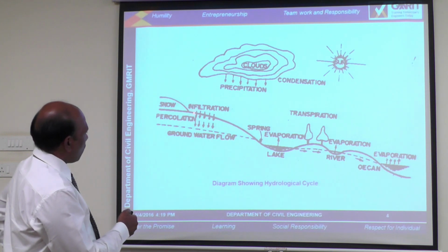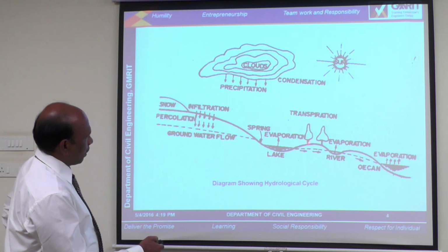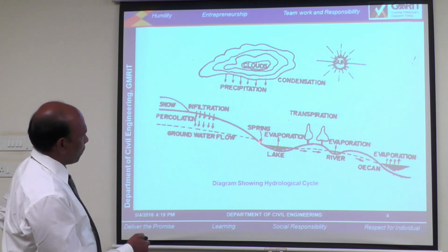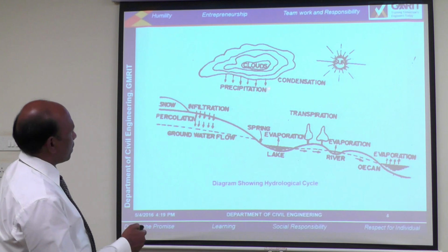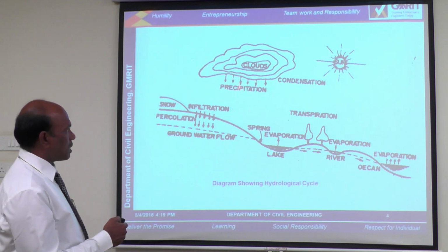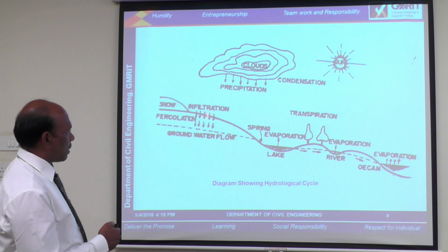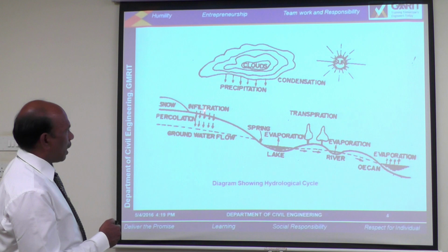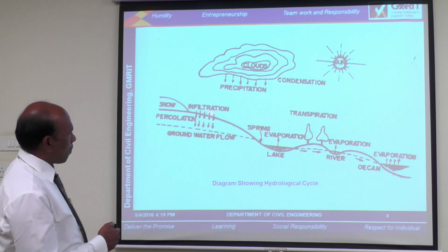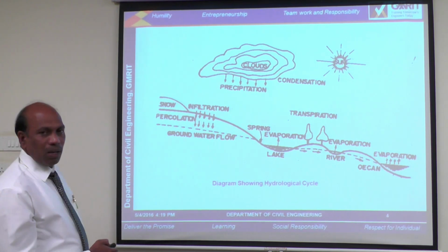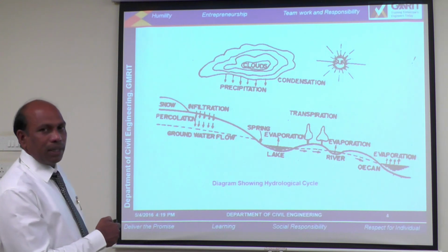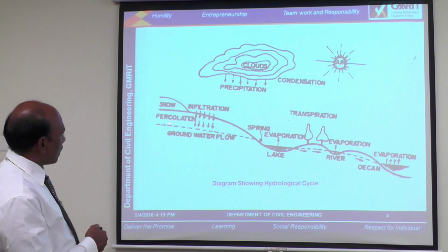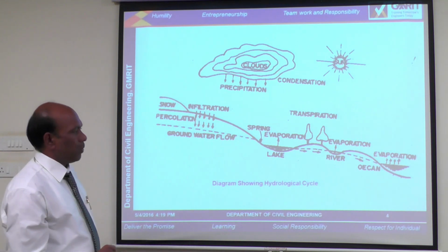This is the groundwater surface, having undulations because groundwater is not in a plane way. Here, this is the precipitation or rainfall. Once the rainfall falls over the ground surface, a part of the water infiltrates into the ground and the remaining part moves above the ground surface. First of all, we are going to discuss the infiltrated water. This infiltrated water percolates down and touches the groundwater table.